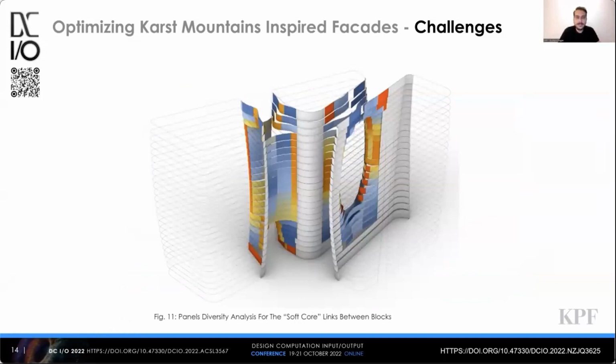So we had to go through another analysis for the internal facade, for wall type 1, 2. All of these panels are single straight extrusions on simple arcs. However, all these arcs are different. Again, it creates a problem to describe the geometry to consultants or to constructors later on.